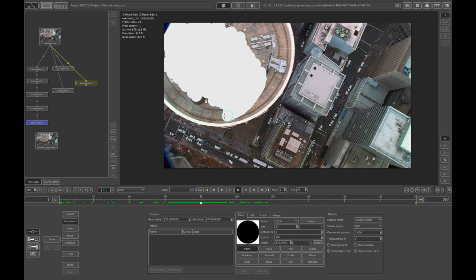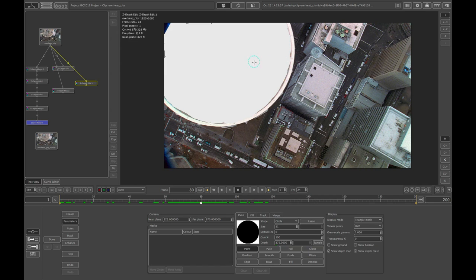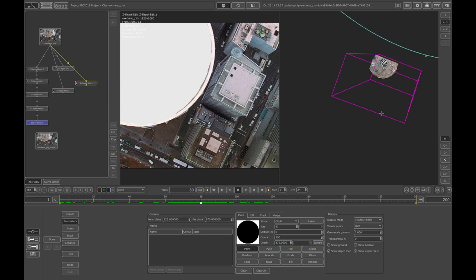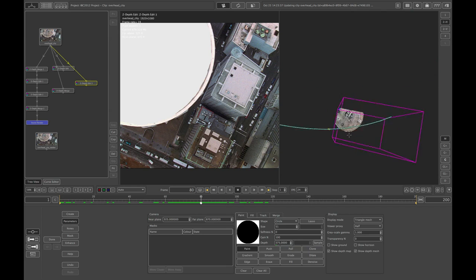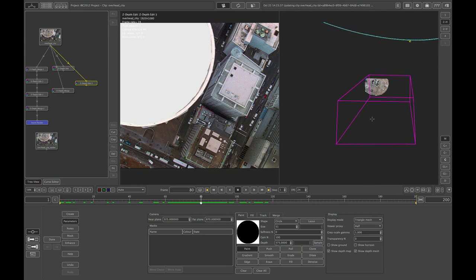The stroke that I'm painting right now represents 375 feet, as I've assigned for this brush. So it's not an arbitrary gray value that I'm just going to lighten and darken and try to get right. This value of gray specifically represents 375 feet relative to the rest of our scene scale. So there's our initial paint stroke for the top of that building.